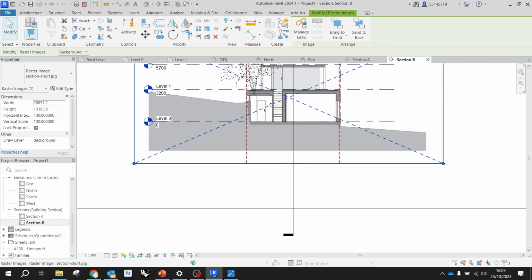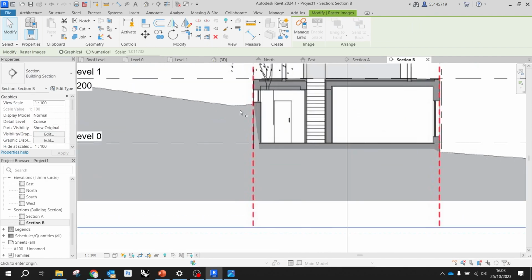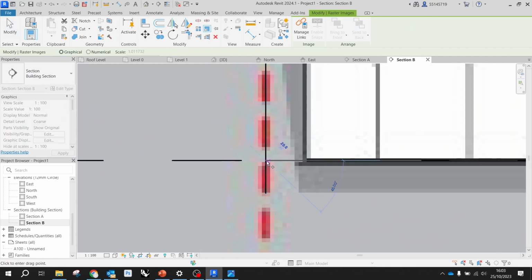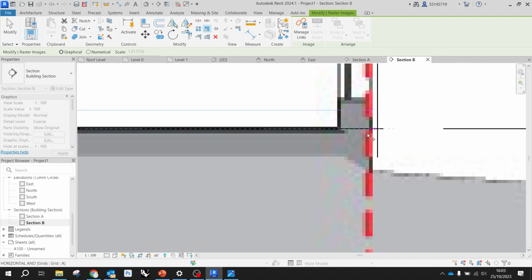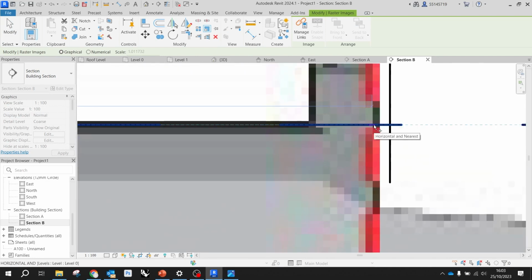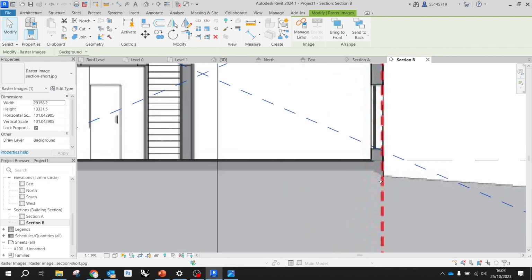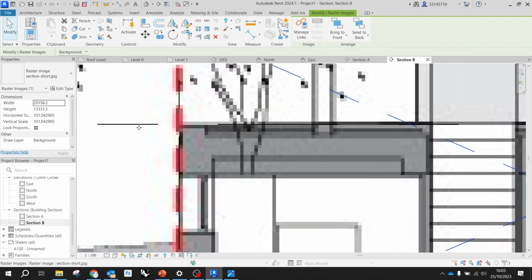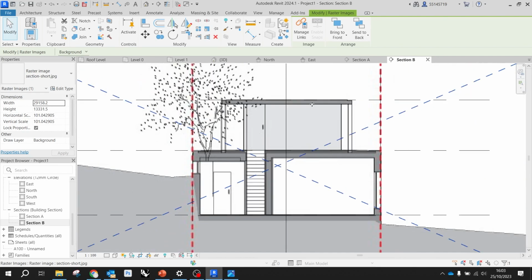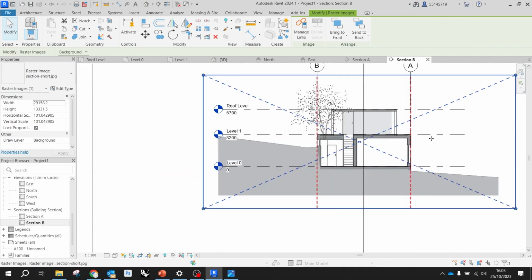So again, selecting the image, scaling from here to where the other red grid is, and make it coincide with my grid. Now it should be perfectly on scale, and you see that indeed the levels are pretty much matching, right? Now all my drawings, sections, and plans are on scale. I have all the information to build this 3D model.